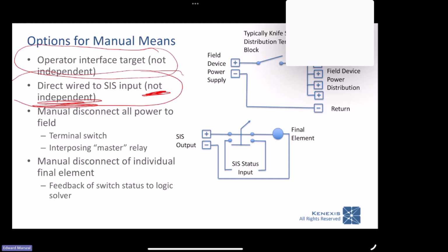But you have to know that they're not independent of the SIS logic solver, and you need to think about, if you're going to use that approach, how available your SIS logic solver is when you're doing this. Most of your SIL 3 rated safety PLCs, you're going to be good to go. But if you're using commercial off the shelf, safety configured SIL 1, maybe you might want to think about something a little bit more elaborate.